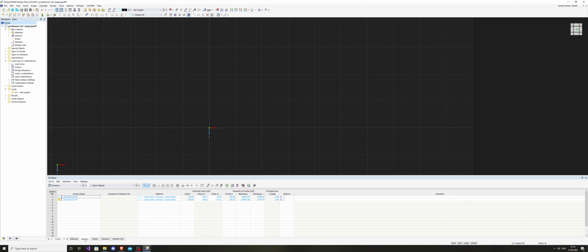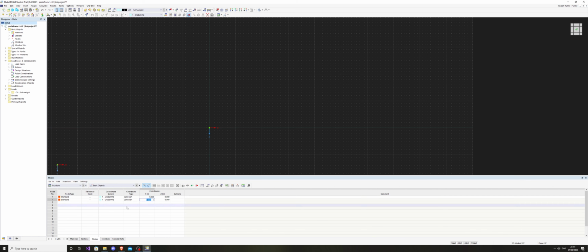So what I need to do now, before I can start making the beams, is make the nodes. For a portal frame, first of all, I'll just use a standard 0, and let's do a 15-meter high portal frame. Because Z is going down, it's minus, so minus 15, so it's 15 meters high.